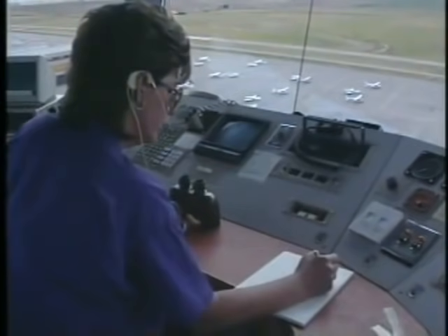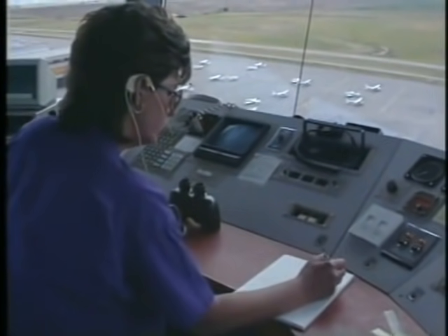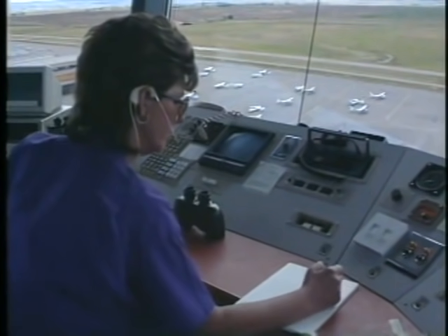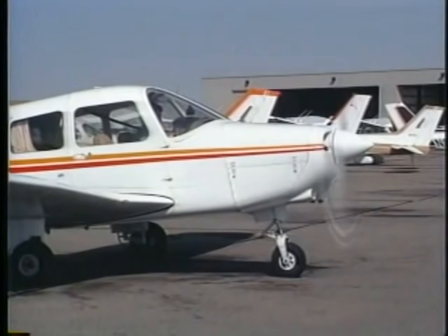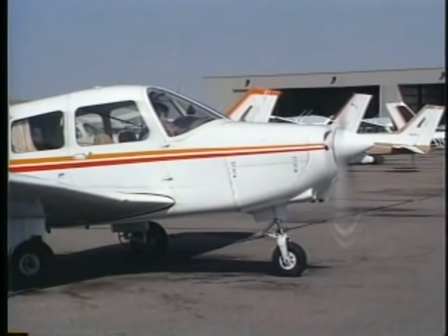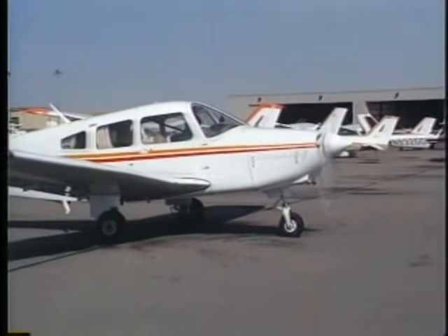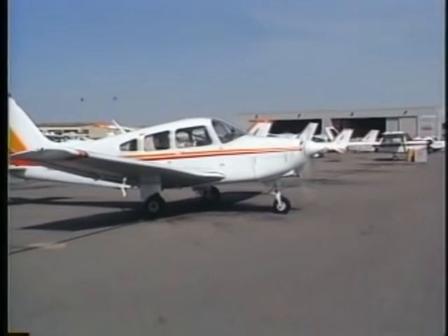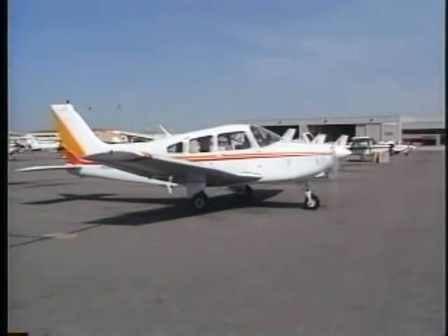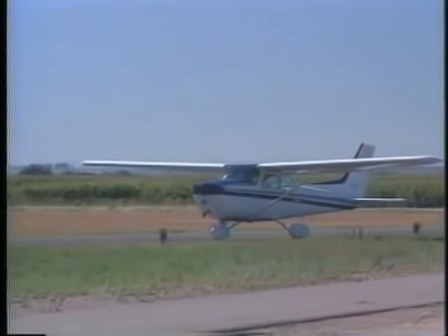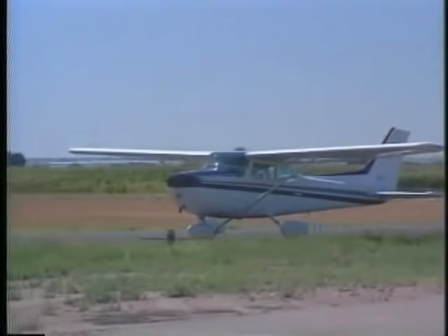At busy airports, clearance delivery is a special frequency designed to relieve congestion on the ground control frequency. Generally, you will contact this facility when you have received ATIS information and are ready to depart. Upon receiving your clearance, you contact ground control when you're ready to taxi. At airports without a clearance delivery, you receive your clearance instructions directly from ground control.